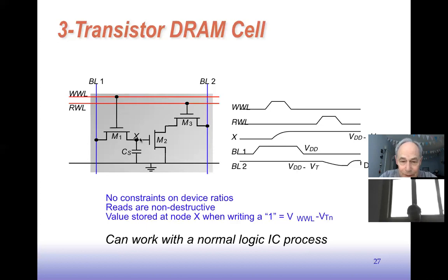As I said earlier, it'll leak away eventually, and it's somewhat temperature dependent, probably on the order of tens or hundreds of microseconds. But if the cell is going to be rewritten or read quickly enough, that's okay. It would have to be recharged from time to time so it doesn't lose its value if it's going to hold its value for a long time.